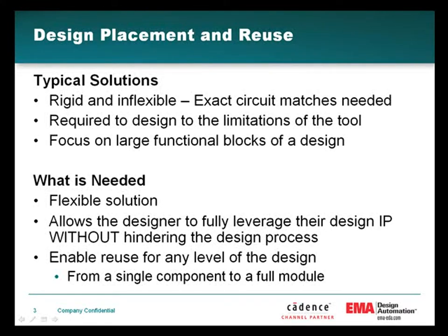With a tool like this, design reuse can be leveraged at any level, from large functional blocks to a single BGA and all its support circuitry placed around it. This type of reuse frees the designer to focus on the differentiating aspects of the product, as opposed to the tedium of repetitive tasks like placing bypass caps in the pin field of your BGA device every time you use that BGA in the design.